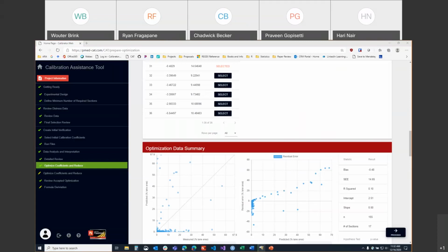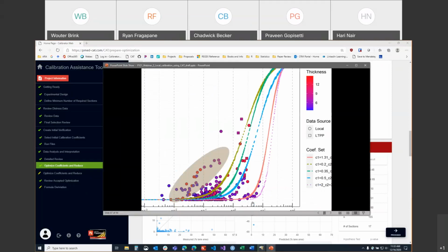I'm sure different combinations could give you similar results, but I'm not really sure, because one affects the slope and the other affects kind of the initiation, and you need to look at the transfer function itself, but they affect different parts of the equation. But if you run C1, if you change that to 0.2 all the way through, and then you decide to change C2, your C1 stays the same. It's going to adjust the slope of this transfer function curve, right?